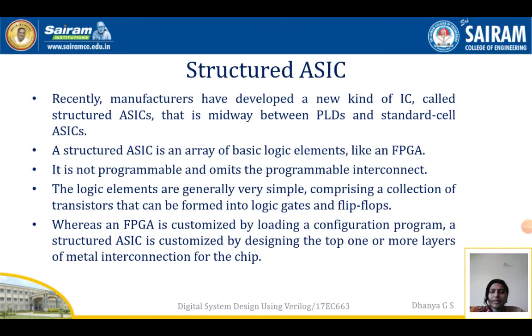It is recently used by all the manufacturers that they develop a new kind of IC called structured ASICs, that is midway between PLDs and standard cell ASICs. A structured ASIC is an array of basic logic elements or components like an FPGA. It is not programmable and omits the programmable interconnect. The logic elements are generally very simple, comprising a collection of transistors that can be formed into logic gates and